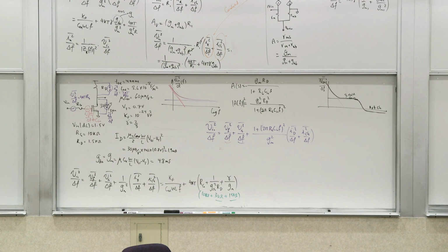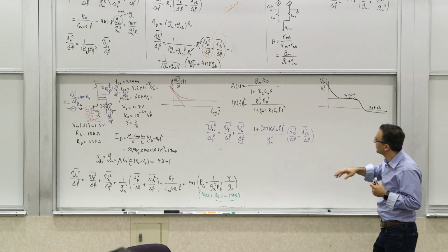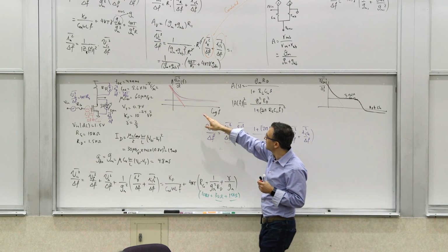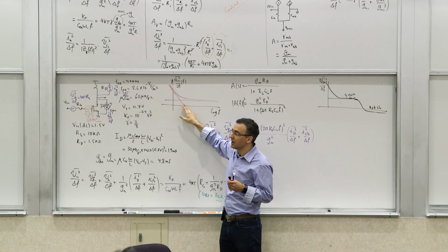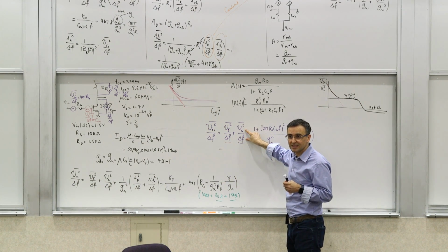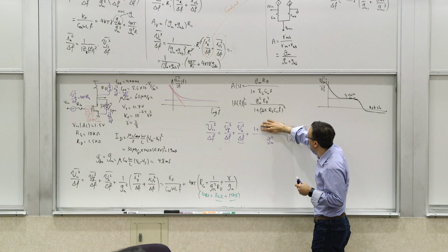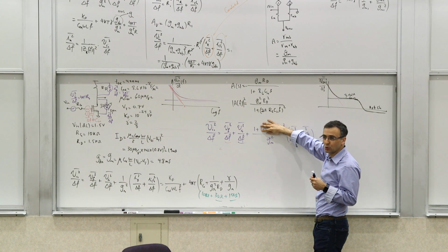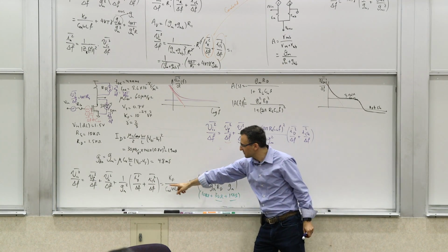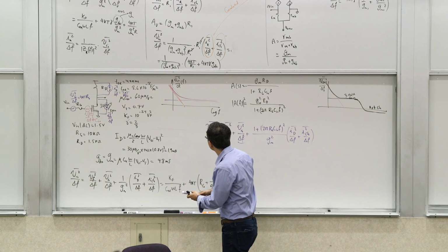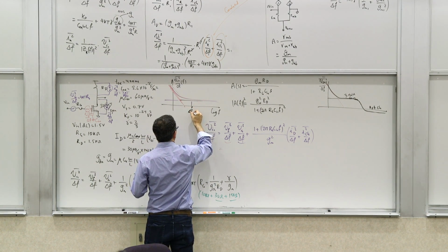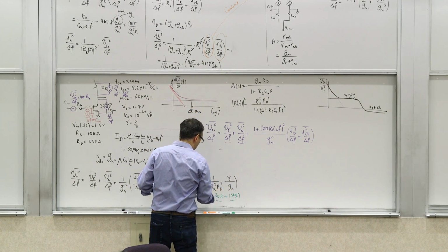But from the input referred noise source, look at this. What happens? Well, this part is that part. That part is not changing. This part is the contribution of the gate resistance, plus, before this kicks in, at low frequency, if the frequency is below this frequency, you will get the same expression as before. So this has all three contributions. So this is all three of them, as before.